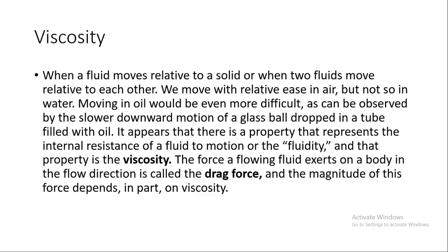On the other hand, in liquids or fluids, if the viscosity is higher, the body will experience greater resistance, the drag force, and will hardly move from one place to another. And if a viscous fluid is moving, it will require greater shear stress to move on. So I think you can easily understand that viscosity is a factor, a very identical factor, associated with different fluids.